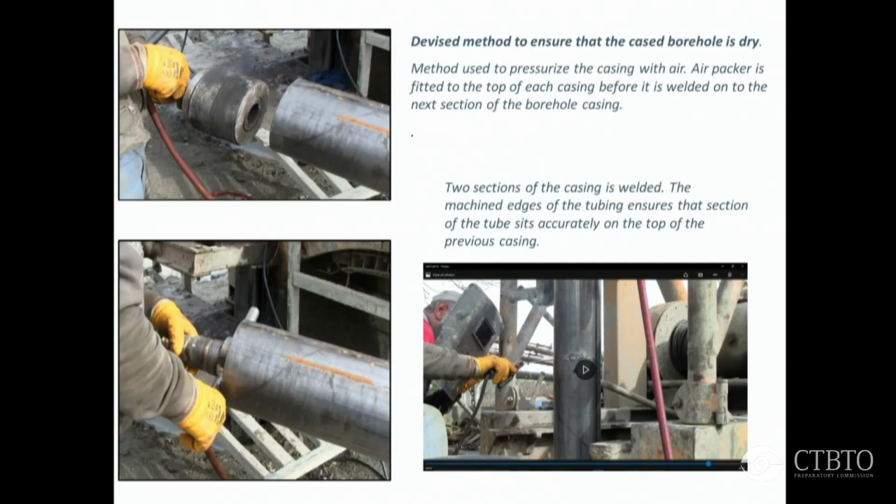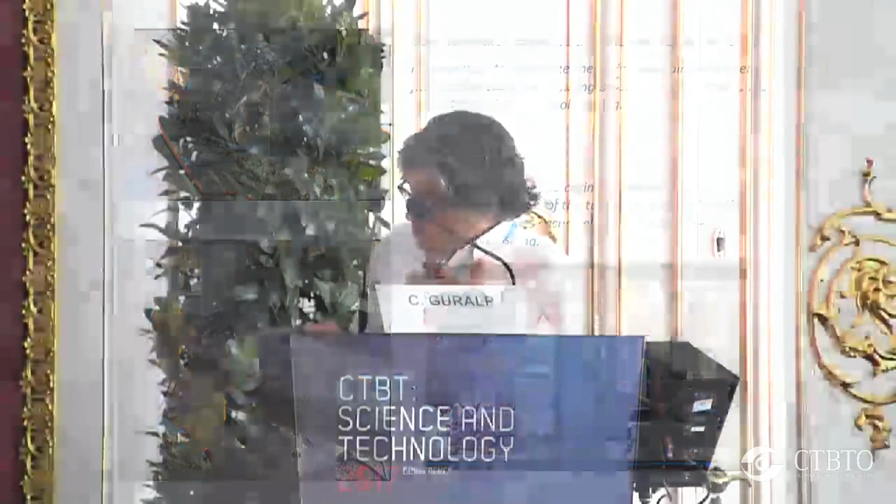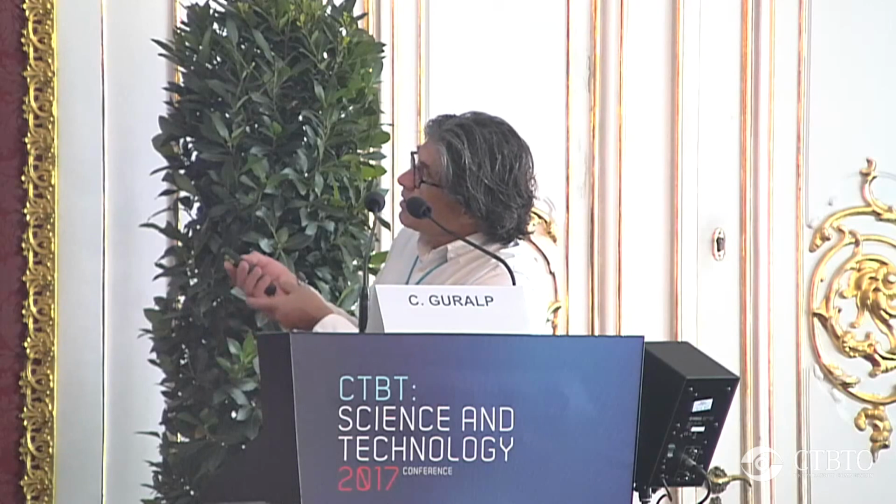Now, most boreholes that CTBTO or anyone has tend to be full of water. The idea here is that we wanted to have a borehole which is dry, completely dry. And trying to make a dry borehole, especially right next to a sea, next to a stream, is not that easy. So we had to devise a technique. A technique had to be cost-effective, and the technique is very simple in that we decided to effectively pressurize each section of the borehole before it was installed. It was pressurized with a little bung, and then we welded it together before it went down.